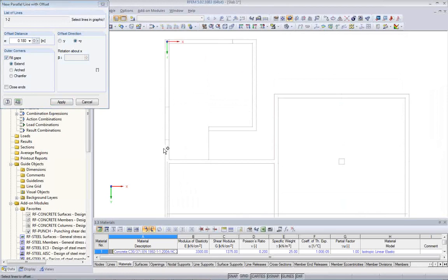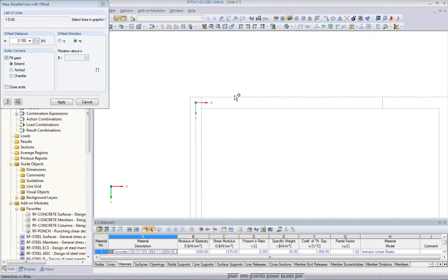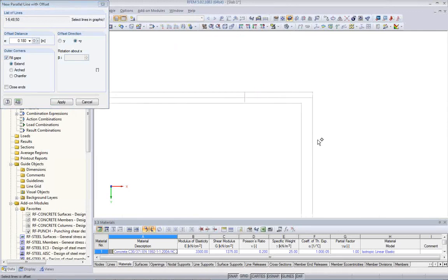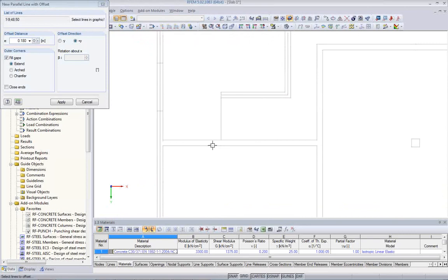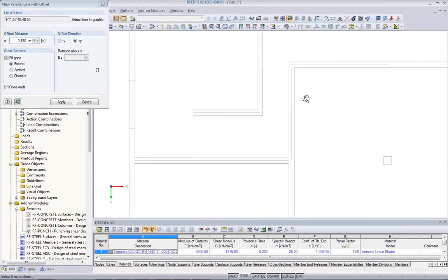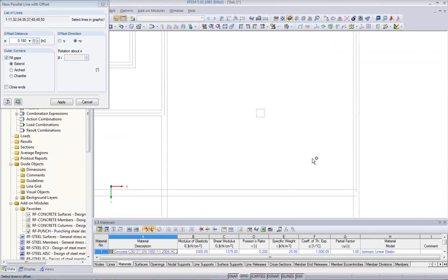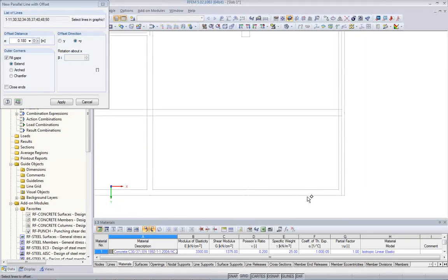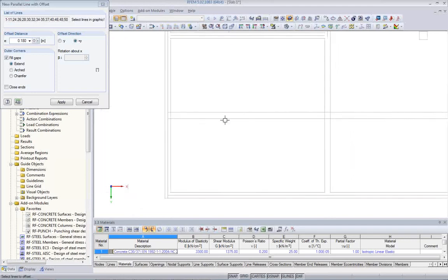And I can now just simply click on all the wall edges that I have in my template and go around the slab here to quickly grab the geometry of the structure from this background layer. So I do not have to use any printed plans or manual drawings, calculate coordinates and so on. So the software is helping me here.